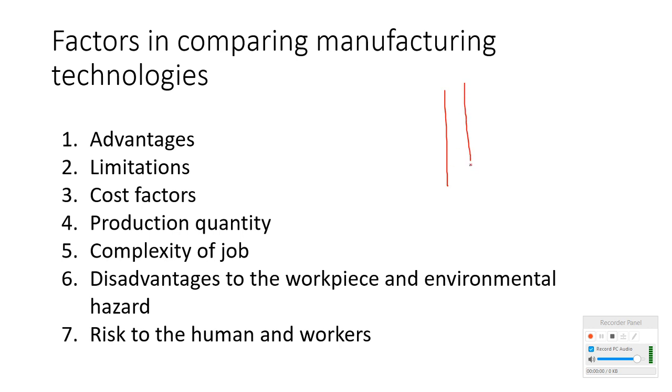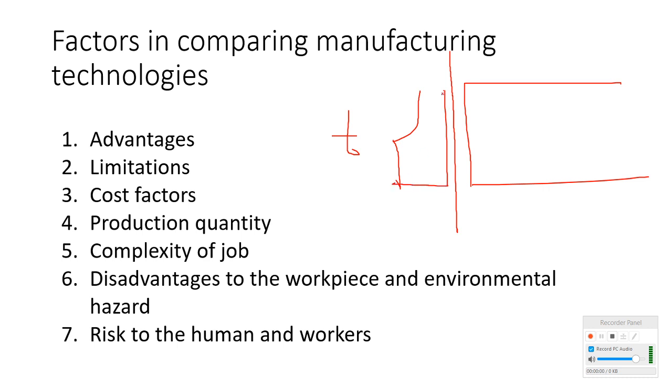Okay, in wire cut, the wire is passing through the thickness. This thickness, this is the part. For example, the area which is cut is almost the same from this edge to this edge. But if it is water jet cutting, depending on the velocity of the jet, if you remember, we could have different types of edge remaining. For example, it could be like this, or it could be like this. So the quality is going to change.